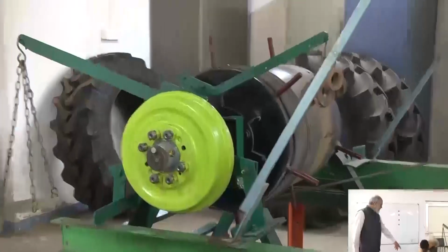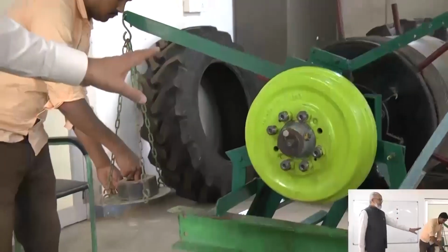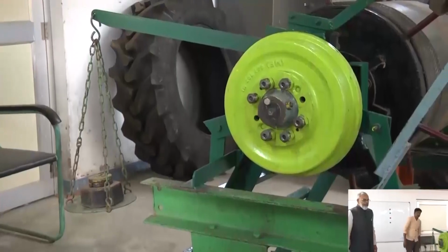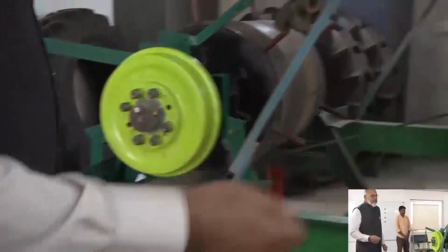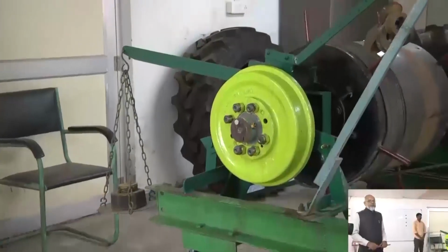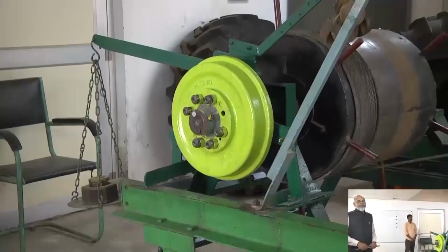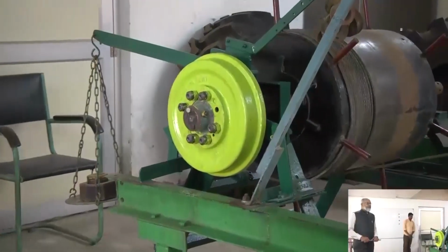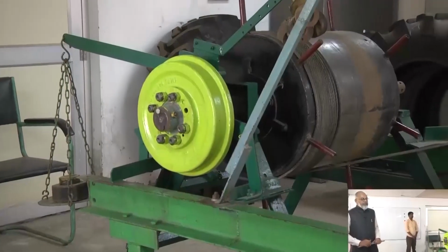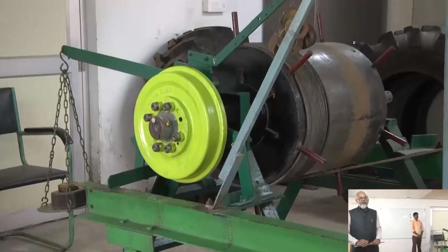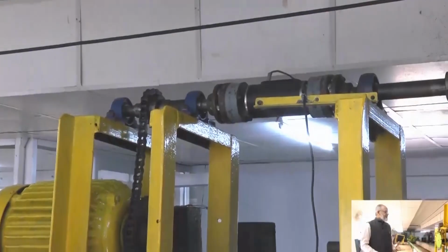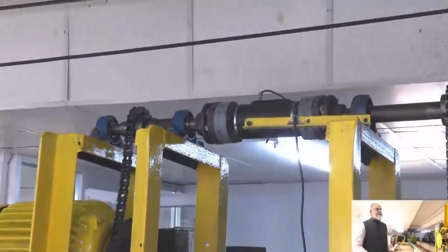Now we will apply load by using some external weight. This is a brake drum dynamometer. When I put some weight, it gives tension to this wire, and thereby it tries to exert pull on the total frame. The frame is attached to the frame of the wheel, so indirectly you are pulling the wheel from behind. That gives you how much pull you applied, and corresponding to that pull, how much will be the slip that you are going to measure. We have to apply power to the axle of the wheel. To measure that power, we need to know how much torque is coming.